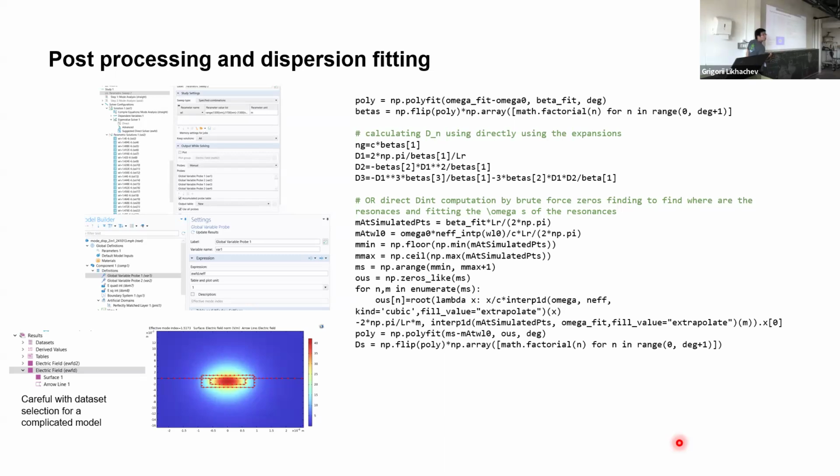For most solvers, because they only have a rectangular grid and do finite difference simulation, you have to discretize the vertical dimension to less than 5 nanometers to resolve this 5 nanometer difference.